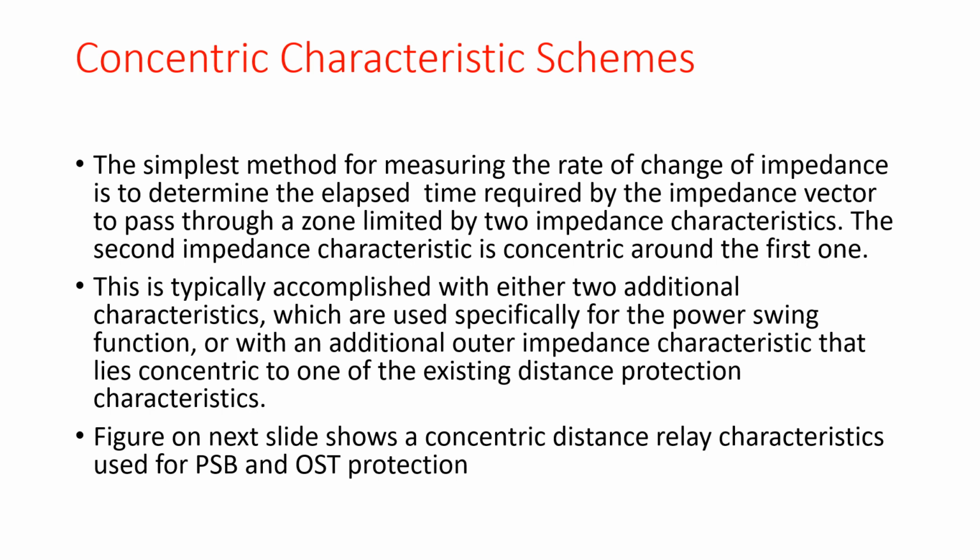So that is an alert sign, and if it crosses it, the rate of change is already being measured. If it crosses or comes closer to the real setting, then in that period the relay has time to block the power swing, or on sensing the power swing it may initiate the out of step tripping at certain predefined locations, so that the system can be run in islanded mode or can be saved from going apart from each other with a large angle.